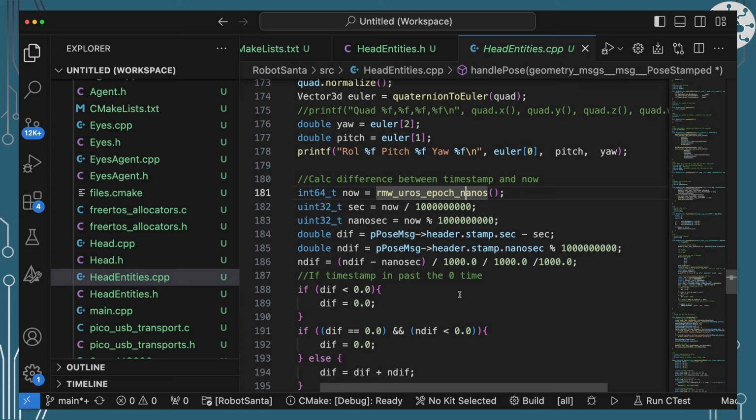Things were flipping. One of the reasons is that if you try to drive pitch in a quaternion beyond minus or plus pi, then you can get some very strange behavior, and you start getting the entire thing flipping, and roll suddenly becomes 180 degrees out.